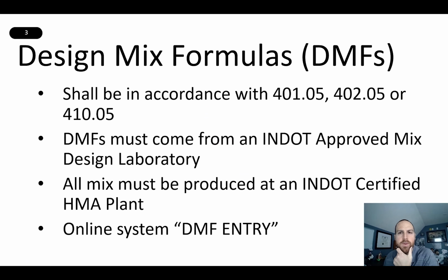Design mix formulas, or DMFs, are the asphalt recipes, if you will. They shall be in accordance with 40105, 40205, or 41005 of the specifications. DMFs must come from an approved mix design laboratory, and all the mix must be produced at an INDOT certified plant. And these DMFs are submitted online through an online system called DMF Entry.